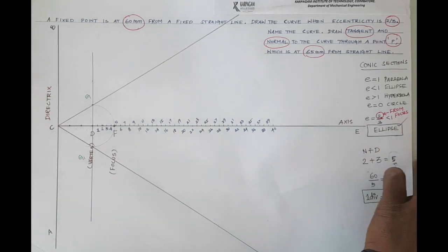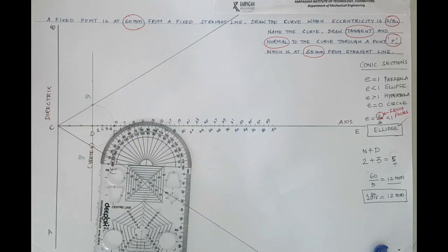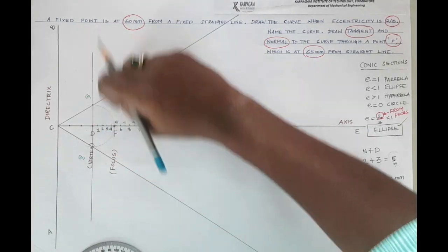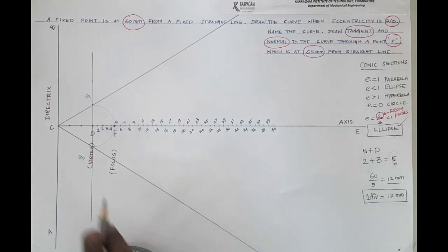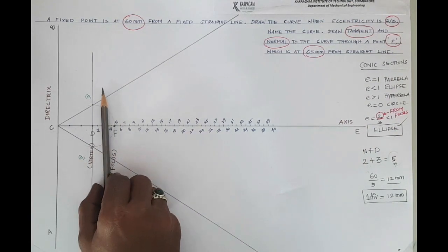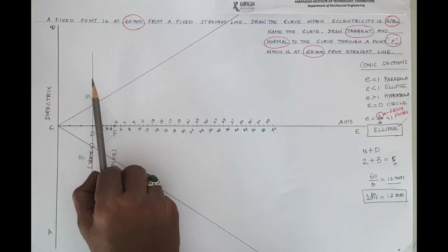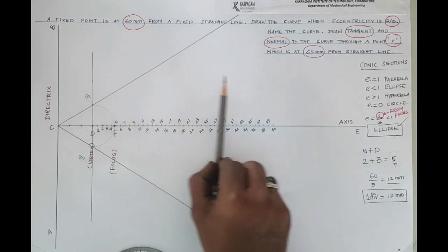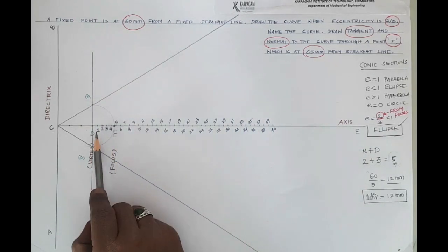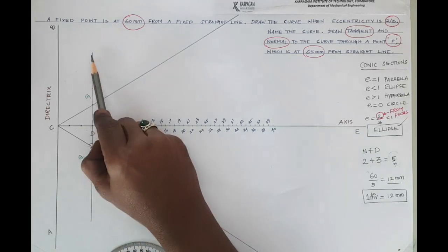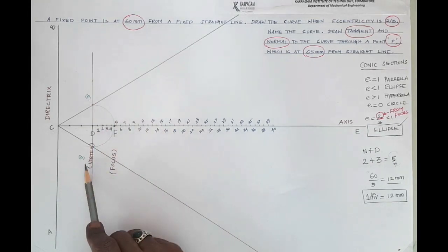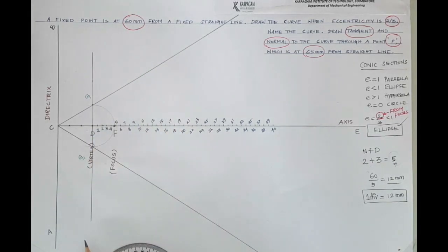Okay. Next, again take your protractor, flow circle or set square because we are going to draw vertical lines from each divisional point, and the condition is all those vertical lines you are going to draw should be parallel to this G1 vertex line.